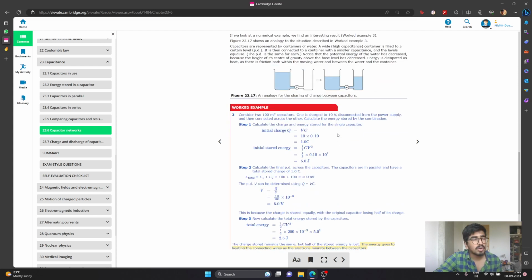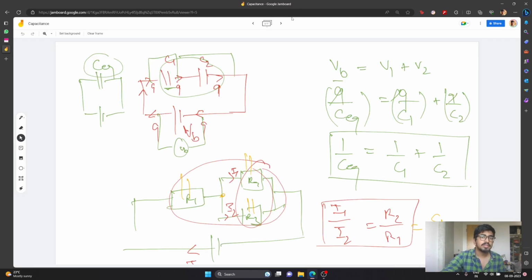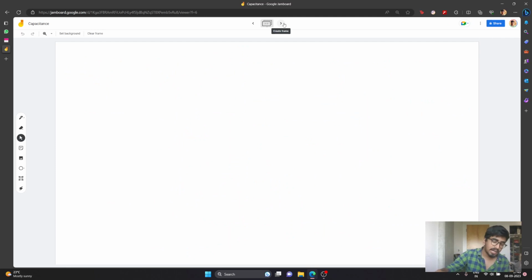Always try to build up a mental picture that voltage on the capacitor is how much it can push, right? So if it wants to oppose, say, a battery, then it wants to have an equal pushing power as much as the battery has, right? So the final voltage will be as much as the battery has. Because the battery has a constant pushing power, in this case this is 5 volts, and at the end this will also be 5 volts, right?